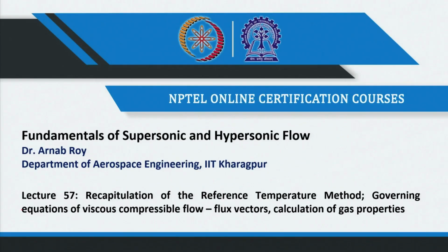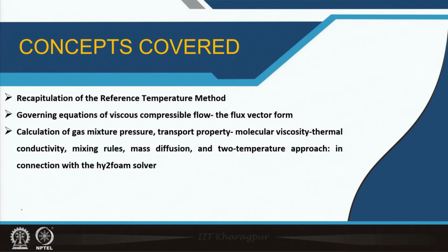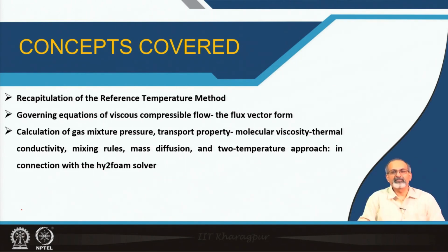In this lecture, let us begin by recapitulating the reference temperature method, and then we will move on to learn about the governing equations of viscous compressible flow by recapitulating them once again, looking at their flux vector form, and then also going into some more details about calculation of gas mixture pressure, transport properties like molecular viscosity, thermal conductivity, the mixing rules, mass diffusion, the two temperature approach. Many of these concepts are not new to you, but we will discuss them once again in connection with the hy2Foam solver in the OpenFOAM platform.